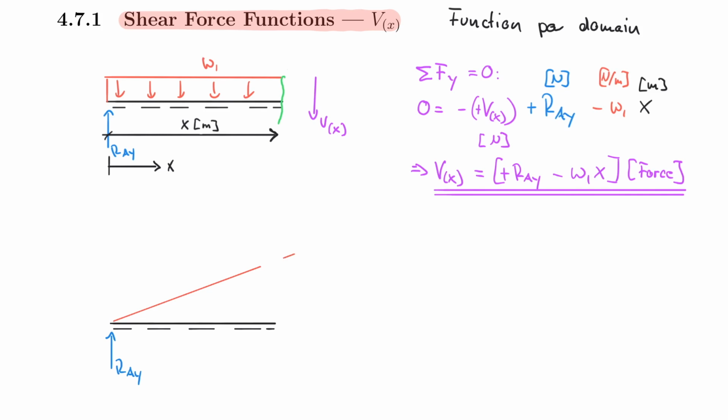And please understand that usually it continues somewhere here. So I'm actually drawing a little bit more than what my cut is, because I need to explain to you in a second how I actually get my values for the slope. But first, let's bring in our unknown, which is the shear force that on the right cut would go down.